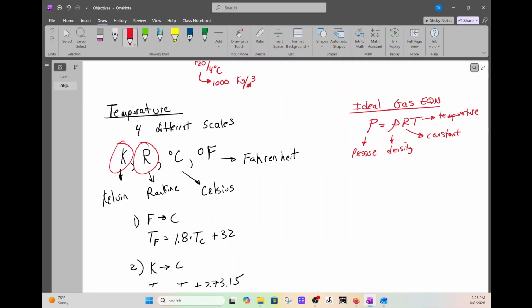So right now in my room or the room you're listening to, we know the pressure, we know the temperature, and we know it's air. We can find that constant in the back of your book. We can find the density of the air in there. Okay. And depending on the temperature and the pressure, the density or kind of the mass per unit volume, all right, will change. This is what we call the ideal gas equation.